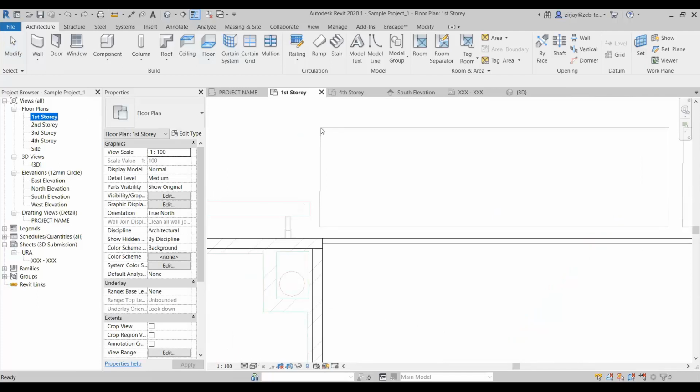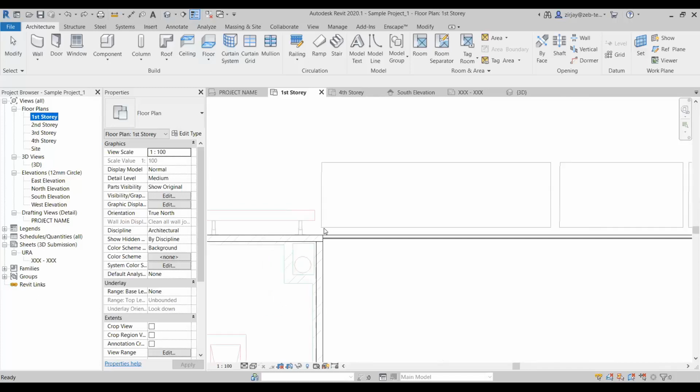But when it goes to IES, since it's not covering a space or a room, it's not gonna translate into a local shade in IES, which is what we want. We want it to be that green colored surface when it comes to IES. That means it's a local shade. So for this, we're gonna use roof.